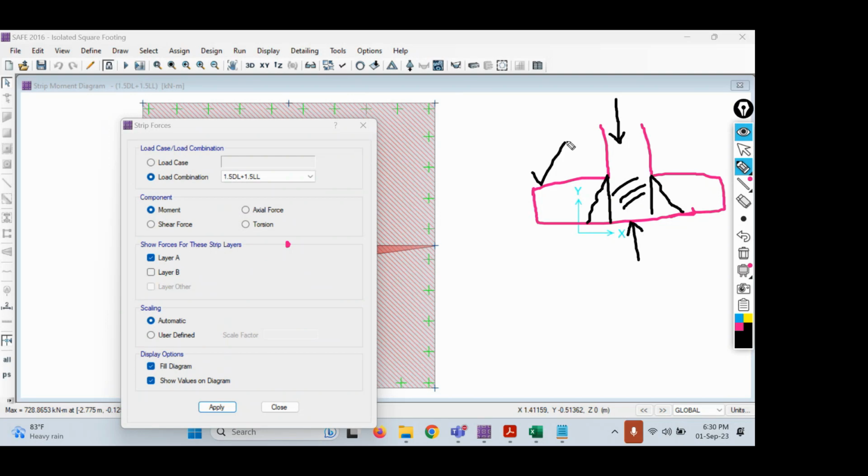But when you look at the sides, I mean this cantilever portion and this cantilever portion, do we have any loads coming from the top? No, there are no loads. So here we have the loads that are coming only from the bottom. What is the load that is coming from the bottom? Upward soil pressure. So in the cantilever portion, we have the non-equal distribution of forces. We don't have the equal and opposite reactions. We have only the reaction forces. We don't have the action forces that are coming down. So for that reason, these cantilever portions are always in danger.